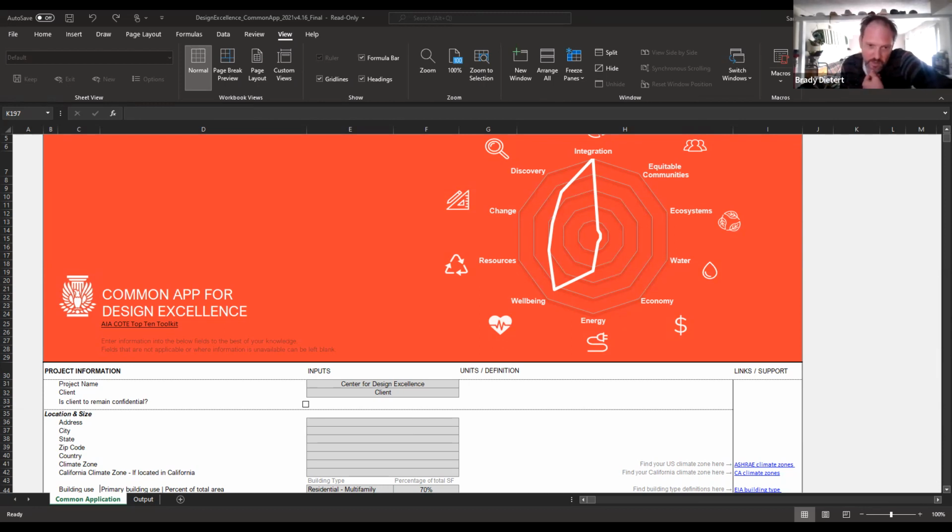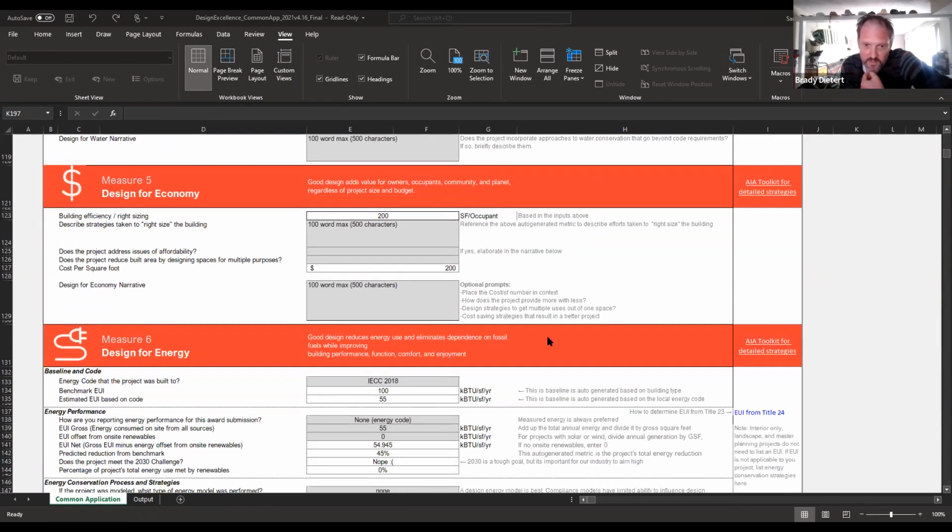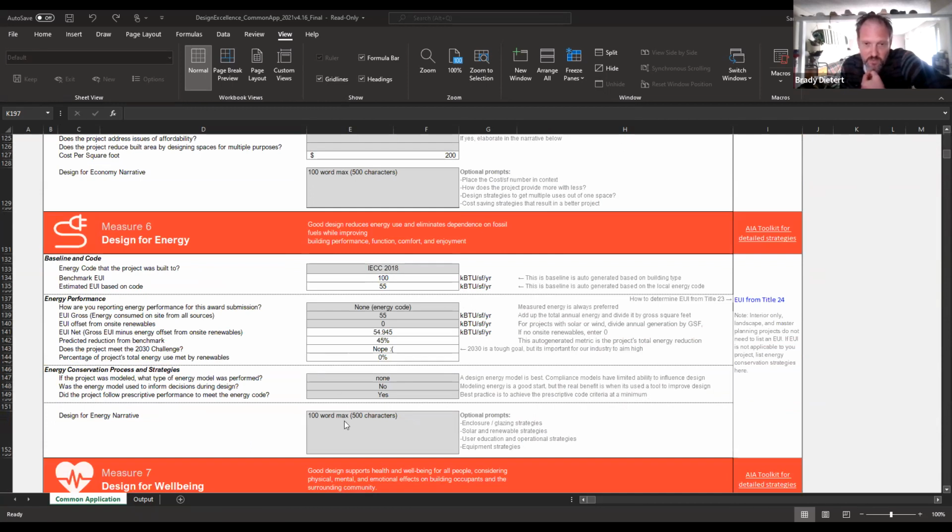I think EUI is really the only thing in this whole document that is very, very technical. Sometimes you might have an MEP engineer on board, and they can give you the projected EUI, or you can use Revit Insight, which is a plugin for Insight. There are other design analysis tools. But even then, the software is only as accurate as the types of walls that you made in Revit, and how much information was in those and the roof.